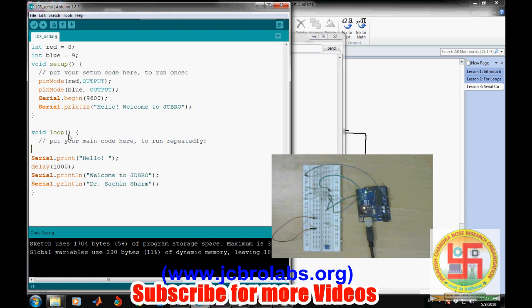Now in loop, let's write digitalWrite red, HIGH, and then send the data Serial.println red LED is on, and then we can provide a 1000 millisecond delay, and then digitalWrite blue, HIGH, and then Serial.println blue LED is on.